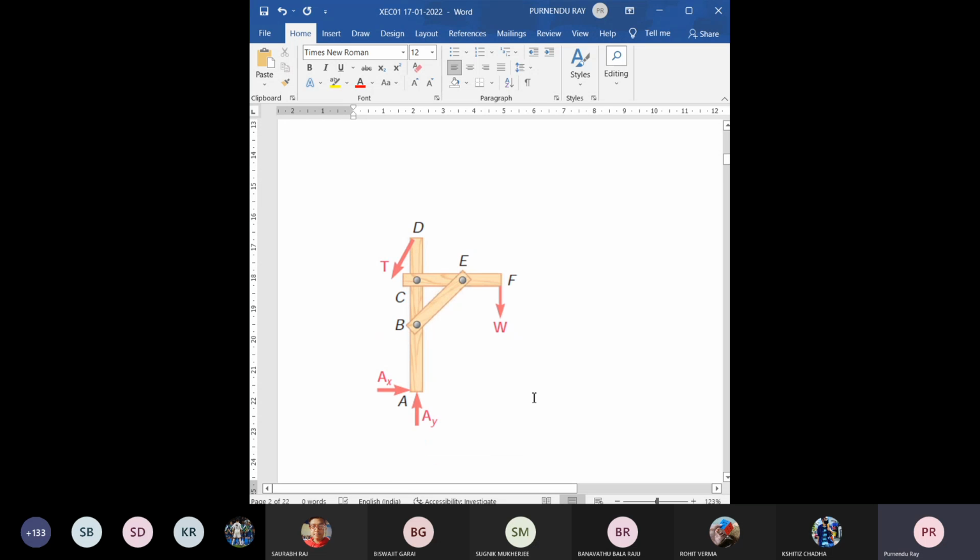It is a 3-force system, applied force W, tension T developed at D, and here is some reaction. Now, condition of equilibrium of 3 forces in a plane. Extend these 2 lines of action, W vertical upward, extend this line GD inclined upward, you get a point of intersection. So primary condition of equilibrium is that the third force, which is in the form of reaction at A, must pass through that point of intersection between the other two forces, that is W extended upward and this T extended inclined upward. This is the point of intersection.